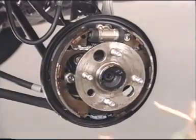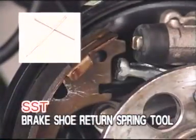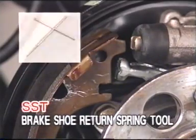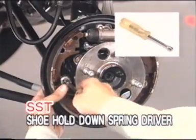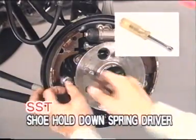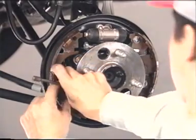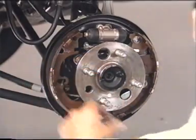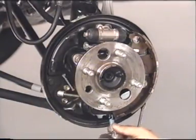First, disconnect the return spring using the SST. Hold the end of the pin and turn the hold-down spring 90 degrees using the SST. Remove the anchor spring and then remove the front shoe.